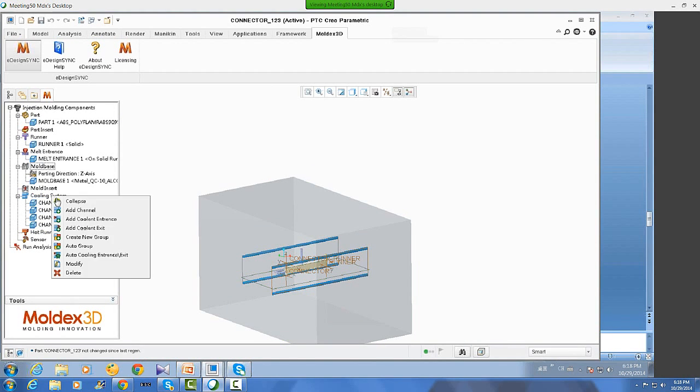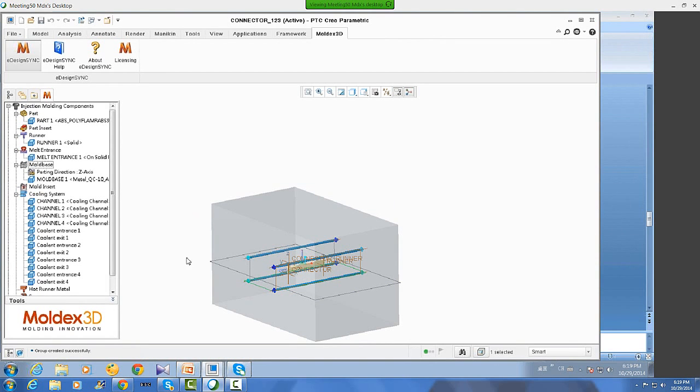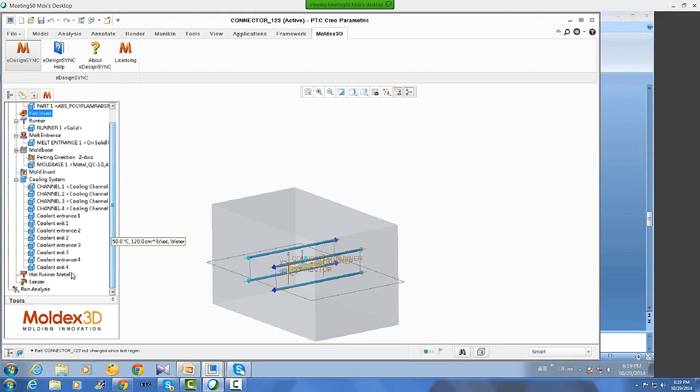And the cooling channel inlets and outlets could be automatically generated after the mold base has been built. And we also offer the possibility to extend this simulation with overmolding and insert molding. And we can also set a sensor on the cavity, and it will respond with the pressure or temperature results versus time to users. And there is another optional function for the advanced hot runner system.